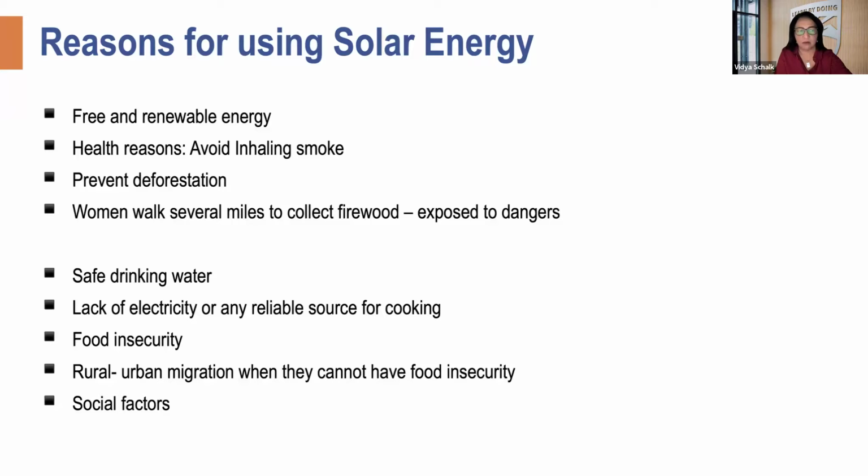Then I briefly talk about the fact that you can use solar energy for safe drinking water. And the United Nations actually has a little kit where they have a little wax thing, a ready-made kit. And you don't need to get to 100 degrees. It's safe drinking water even at 70-plus degrees. The wax starts to melt at that temperature, and then they know it's ready. They can drink that. One of these days, I do plan to get that kit.